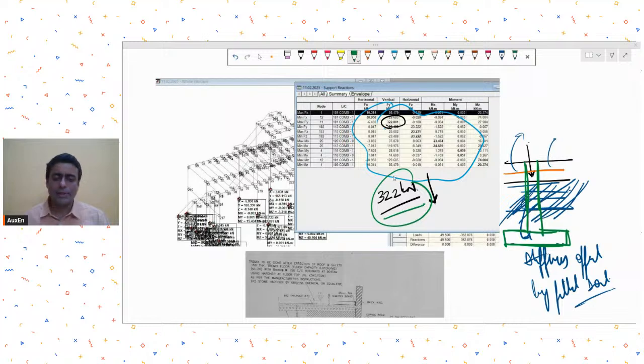So go for a pedestal footing type of thing instead of just anchoring to the floor. That is my suggestion in this case. And for chemical anchors, if you want more information, you can get in touch with these applicator companies, they will provide you the necessary capacity calculations.